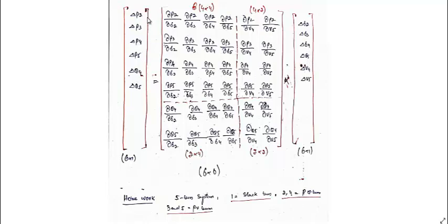That is, these deltas are unknown for all buses except the slack bus, and V4 and V5 will be variables for bus number 4 and bus number 5, the PQ buses. So then it is simple. We have to form these elements by simply differentiating these equations with respect to these variables.